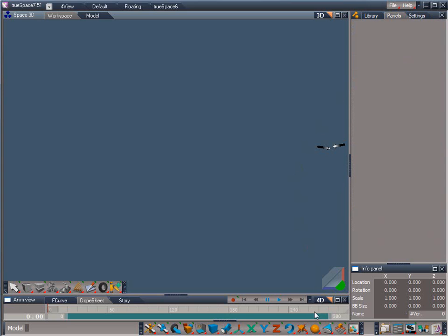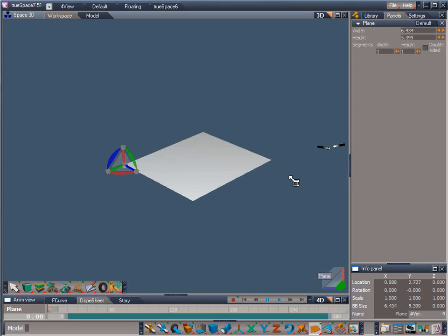Now click on the Primitives flyout and select the plane icon. With the plane tool active, draw out a plane in the 3D space. Now right-click in an empty area to exit the tool. We know our fish template is 800 by 600, and we want to maintain that same aspect ratio. So in the plane panel on the Stack view, change the dimension values for the plane to 8.0 for width and 6.0 for height.